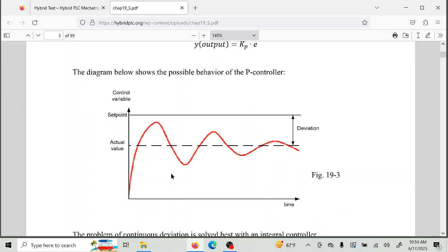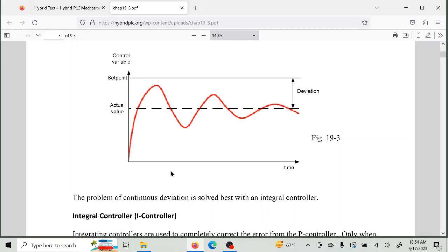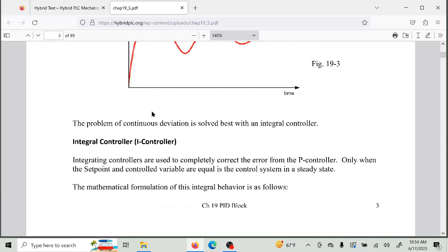The P controller has that fallacy, but we accept that to an extent. But for really good accuracy, obviously if this is my real set point, I can lie and say move the set point up here when it's really down here, and I've got a good set point with just a P controller. I understand that, but that's not what we're about. I want to make my set point, have it go up to that, then stabilize there and be a good set point there. Even though we could lie and set it up here, this is our real set point, so that's what we want.